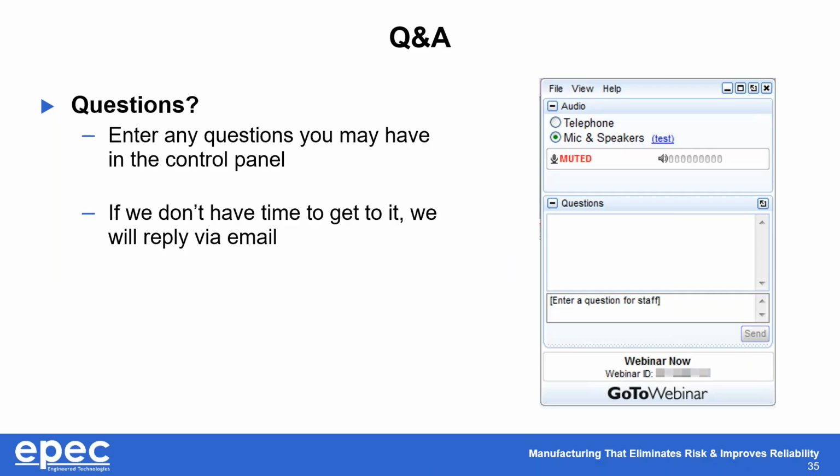The next question here is, is there such a thing as a double-sided heater? This is a good one. I've actually never thought about this, but the answer is, all heaters are double-sided. It's just a heating element with film on both sides. So in theory, the heater is double-sided. The key is that some customers only put an adhesive on one side and affix the adhesive to another member on that one side. But there are situations we've seen customers that will take a heater and sandwich it in between 2 plates so that the heat goes in both directions.